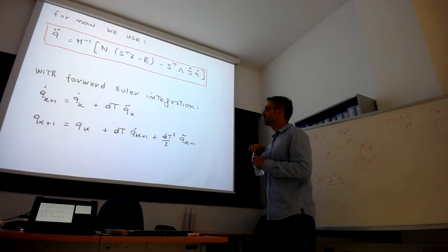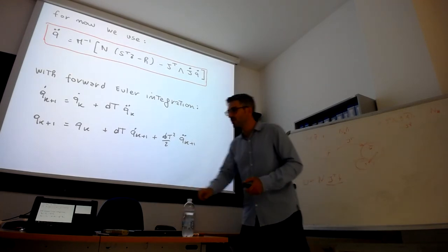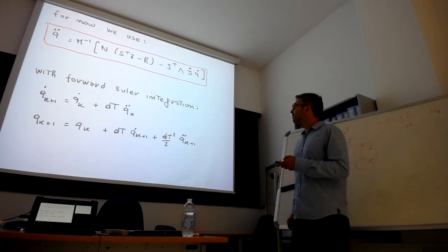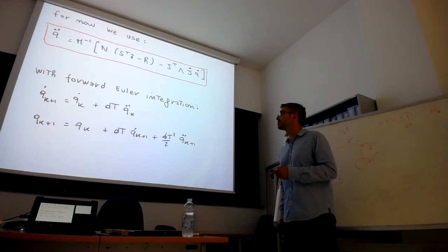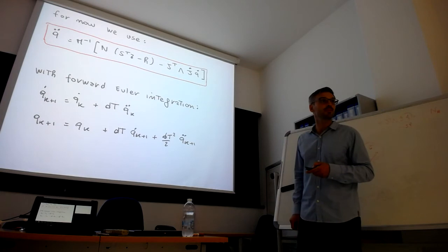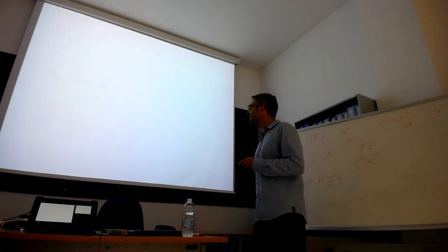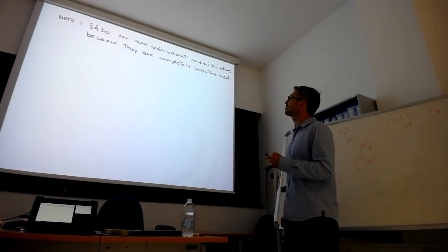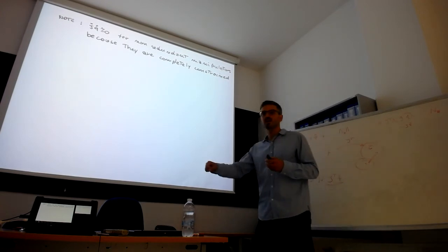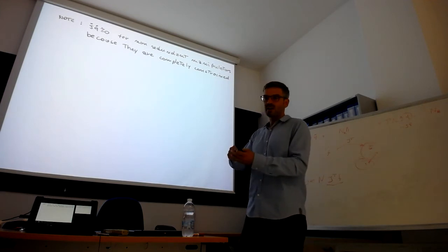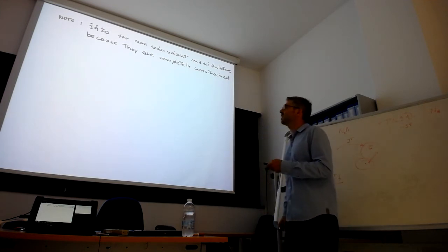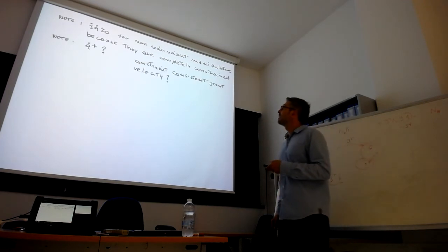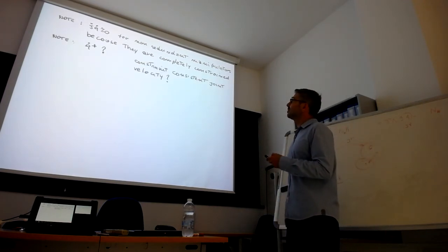And let's say we are using for now the forward integration approach to compute from the acceleration the velocity and the positions. And this will be contact consistent. But yeah, this is a detail. This term is almost zero for non-redundant manipulators, because in a non-redundant manipulator the task dictates the motion of the joints, so you don't have anything in the null space. No motion in the null space.